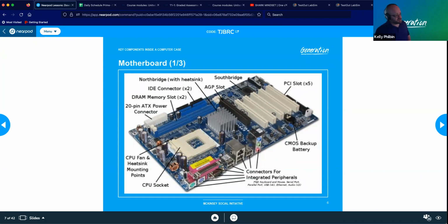Right here, you see a bunch of connection ports, which if you looked at the back of your computer, all of these would look kind of familiar to you, because this part of the motherboard actually would stick out the back of your computer. So you've got your audio connectors, which look like your headphone jacks, otherwise known as 1/8 inch jacks. You got some USBs here. You have a network connection or an RJ45 right here. You got your DB15, which is an old school monitor connector, and you have your PS2 connectors, which are good for your keyboard and mouse. These are older connectors. We will be going over these again. This is just showing that when you look at the back of the computer, you've probably seen a lot of these before.